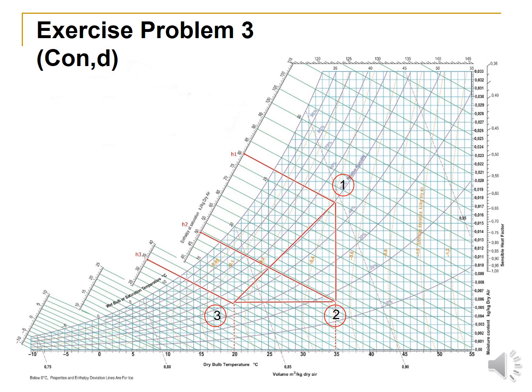So from the data, point number 1 and point number 3 have been plotted over there. So this is the process line actually. And for the sensible heat factor, we will resolve this line into rectangular components in order to calculate the sensible heat and latent heat.